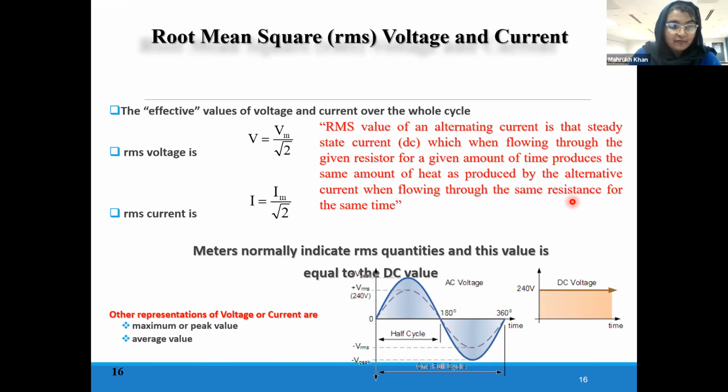So the average value of the sine signal is 0 because the parts cancel each other out, okay? So with RMS, we need to know how much equivalent average power your sine signal is transferring to the load, equivalent to a DC voltage. That's what RMS tells us.